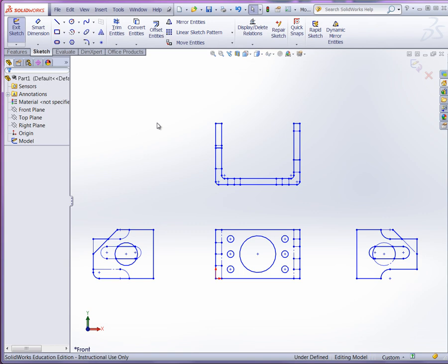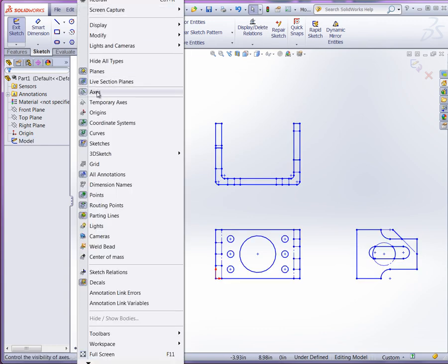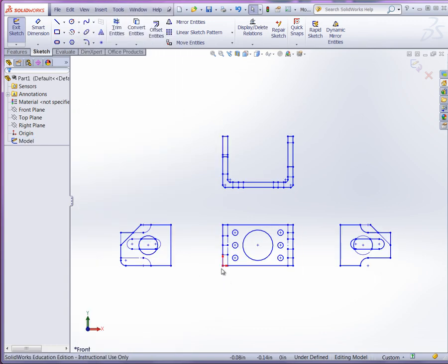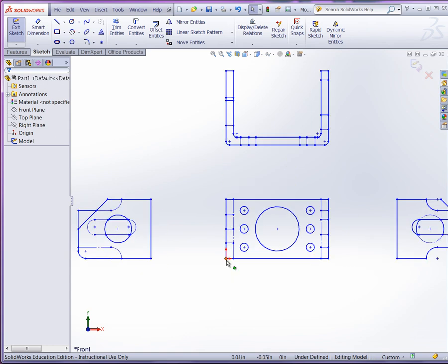And now you'll see here a representation of the 2D geometry. Once you're back into the SolidWorks part model, you can see that it automatically created a sketch, but you don't even see the sketch here. All you see is the sketch called model, and it contains all of the line work. But now the task at hand is to assign all the groups of line work to a specific sketch, and therefore a specific plane. Now again, if you take a look at your view and you turn on your origins, you'll be able to see the bottom left-hand corner here shows the origin. And so you could assume that this was the origin in the AutoCAD file as well.